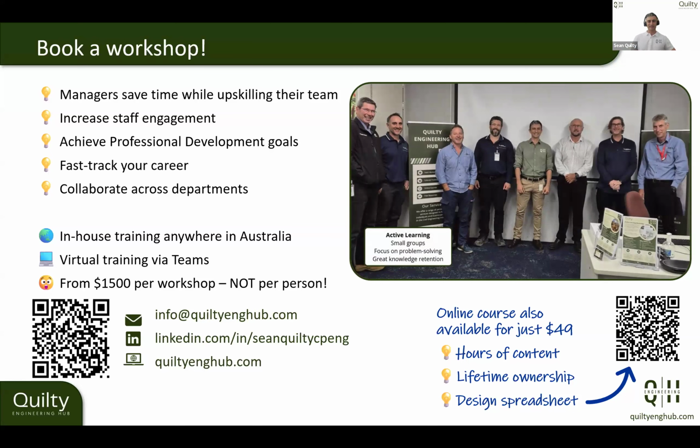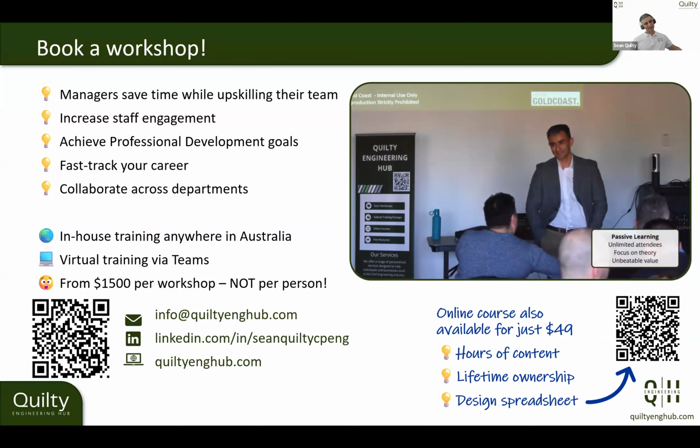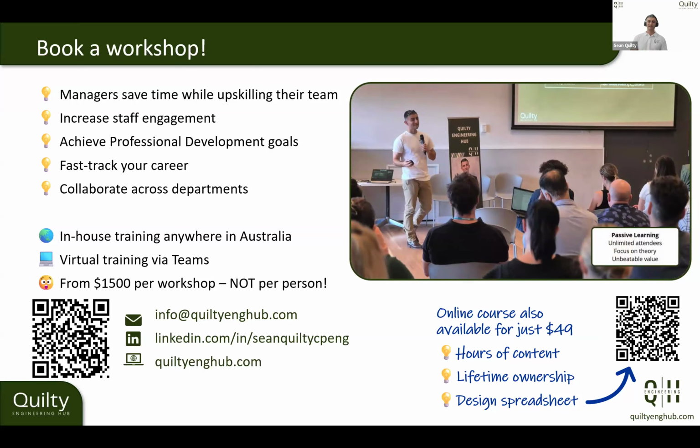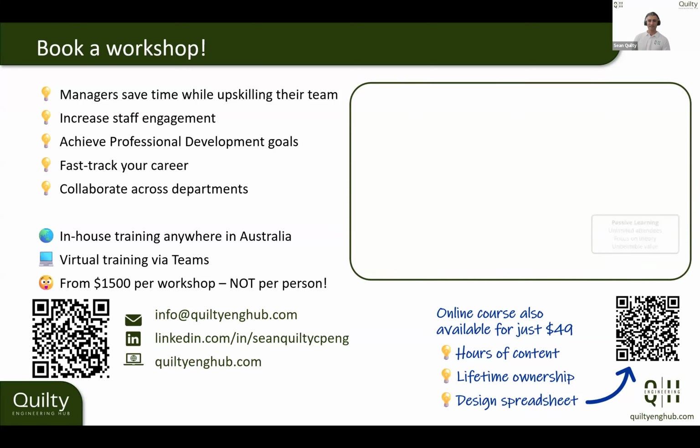Whereas you could have maybe half that depth, only half a meter deep, and you think, oh, well, that's safer. But if that velocity is screaming at 4 meters a second or something, the pure momentum of that will actually knock you over. And so that's the philosophy behind depth velocity product. So that's probably one thing I'll check.